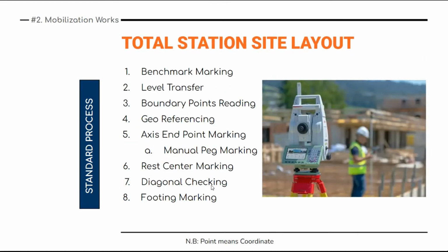The next is total station site layout. It is not that difficult though, but it's skillful work. For that we will be having a separate field training via this video knowledge sharing basis. So here you just need to understand the basic principles of how the total station site layout works. Okay, so here what you have to do is create a benchmark. From that benchmark, that is the temporary benchmark TBM, just transfer the level to the entire plot.